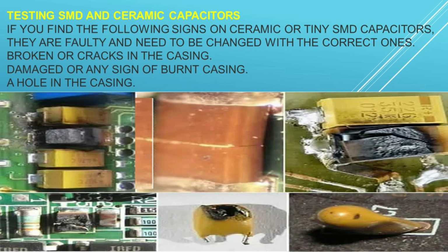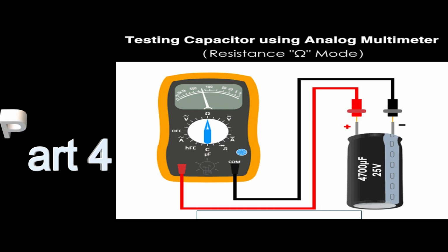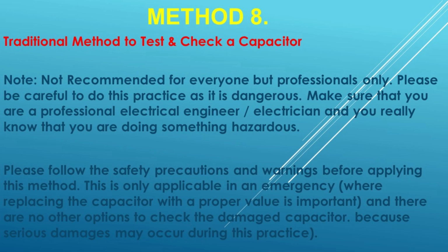Bulging top vent of capacitor. The top vents of the electrolytic capacitor in shape of K, T, or X are the weak points made to release the pressure during the failure of a capacitor to avoid serious damage to the surroundings and any other components connected near to it. If you find a bulging top of the capacitor, or electrolytic discharge, black, white, or orange in color, which depends on the electrolytic material, the capacitor released gas pressure during failure and broke the top vent of the capacitor.